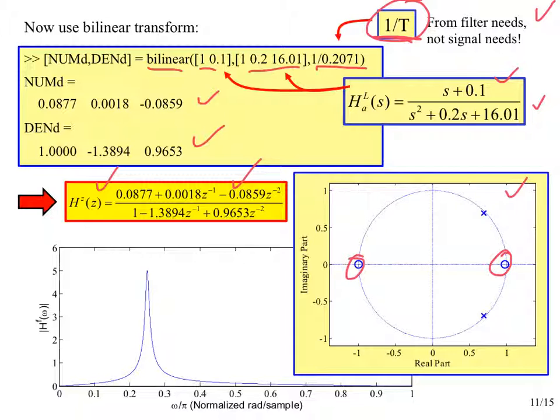So one tacking things down near zero frequency and one tacking things down up near pi. And then we see two poles very, very close to the unit circle that are causing the resonance, and they are exactly located at pi over 4 radians on the angle on the unit circle, and that corresponds to pi over 4 radians per sample. And this is my almost always used normalized scale.